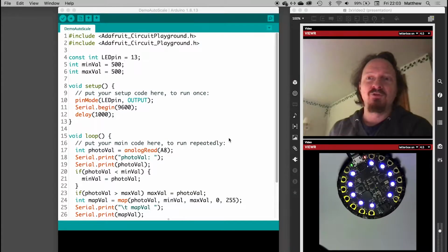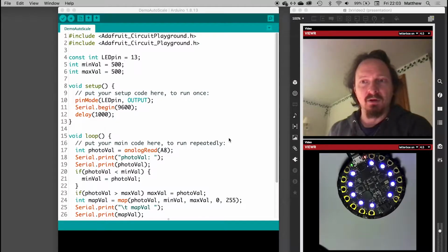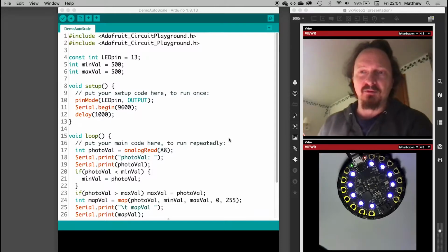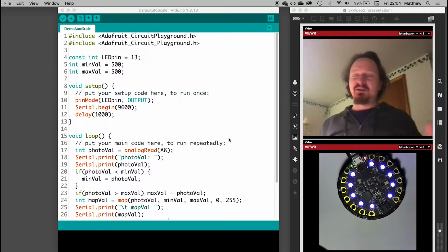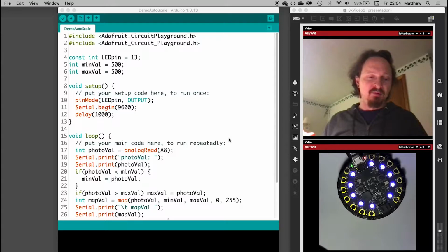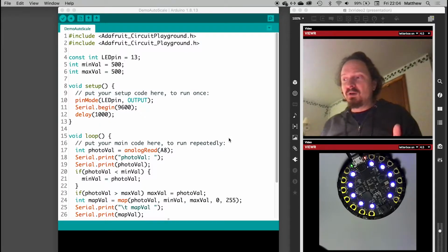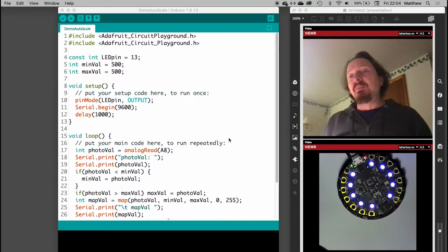All right, so I had mentioned in the last video that your input for an analog sensor is going to change based on the environment, right? So in some environments, that 0 to 1023 range, you might never see the full spectrum of it. You might only see like 0 to 850 or from 200 to 900. It really depends on the environment and the sensor you're using.